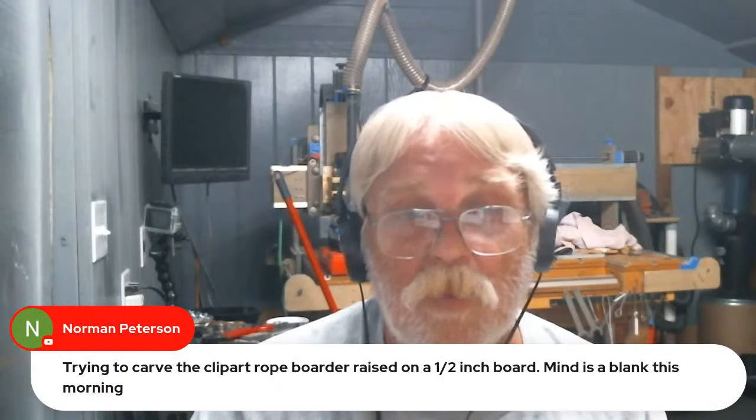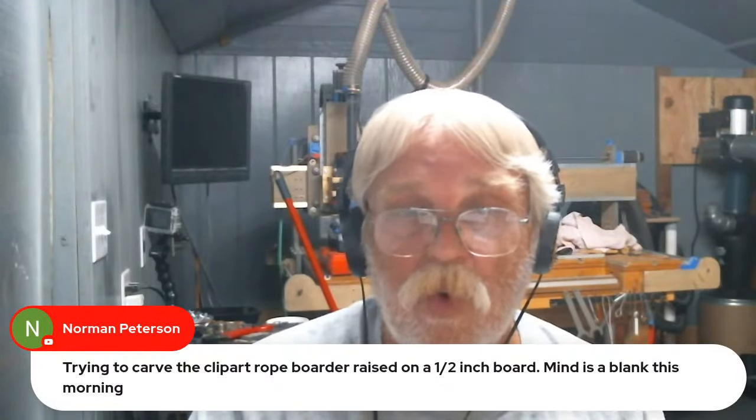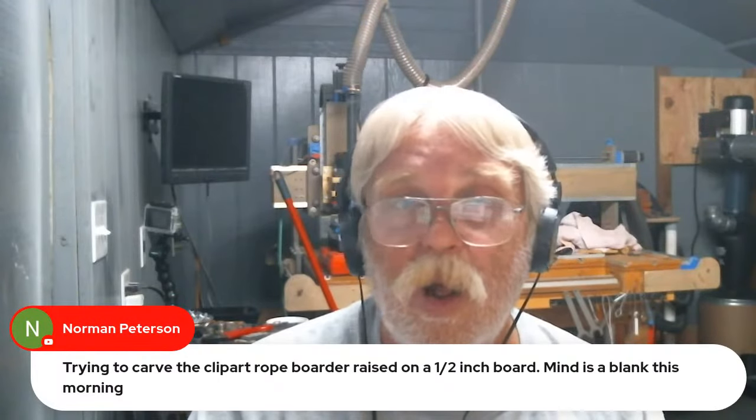I'm trying to find you, Norm. Okay, there you go. Trying to carve a clip art rope border raised on a 1/2-inch board. Mine is blank this morning. What are you having an issue with? I mean, is it placement, or is it adjusting thickness and what have you? And that's simply done in the modeling tab with the wrench, and that'll do your model height.